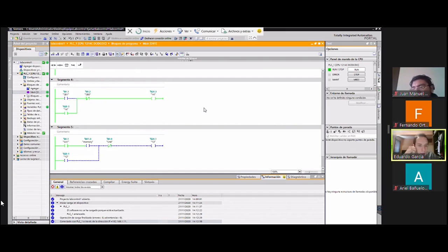Okay, in segments 4 and 5, we control both cylinders' retraction action. We use in segment 4 the sensor SB1, that's when the cylinder is extended. We sense when it's extended. And we have a normally closed SB0, so that when it retracts, it no longer sends the action J4. That's the B cylinder retracting.